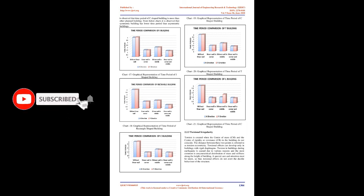2.2.3 Torsional irregularity. Torsion is created when the center of mass, CM, and the center of rigidity or resistance, CR, in the building do not coincide. The distance between these 2 points is referred to as torsion eccentricity. Torsional effects can develop only in buildings with rigid diaphragms. Torsion in buildings during earthquake is caused due to various reasons, and the most common is unsymmetrical distribution of mass and stiffness along the height of the building.